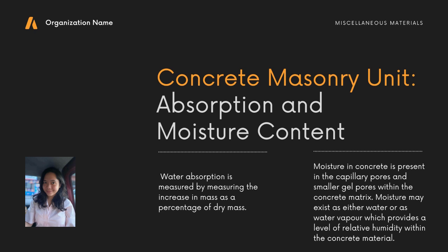The first, oven dry, means exactly what it sounds like. The aggregates, which contain pore spaces of their own, have those pore spaces filled only with air. The second, saturated surface dry condition, is defined as the condition in which all of the pore space within the aggregate is full of water, but no water is present on the surface. Both of these are laboratory definitions.